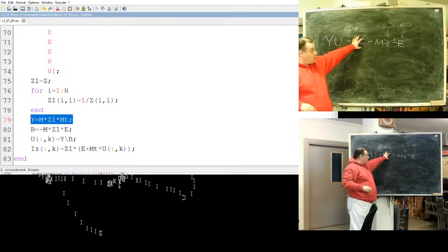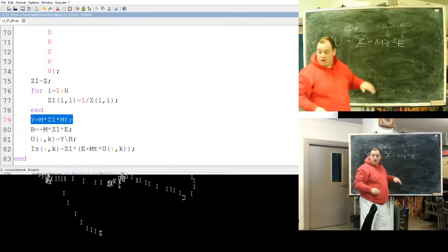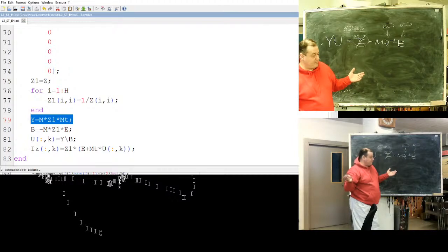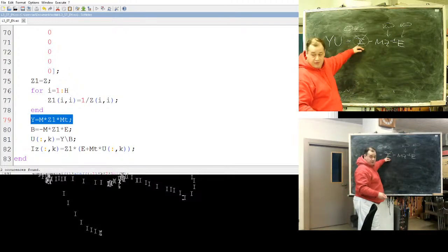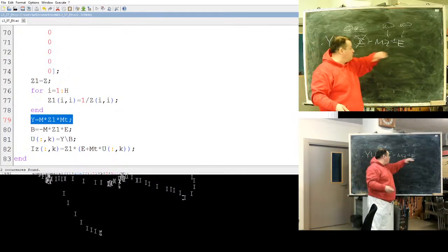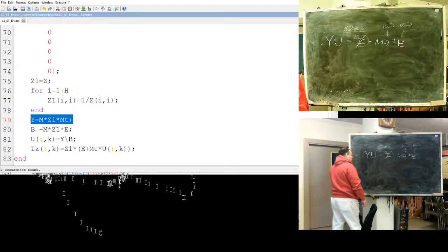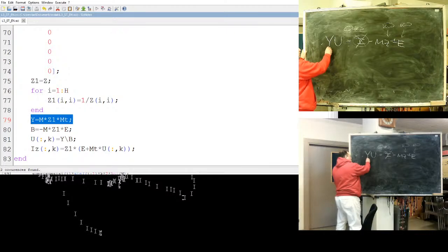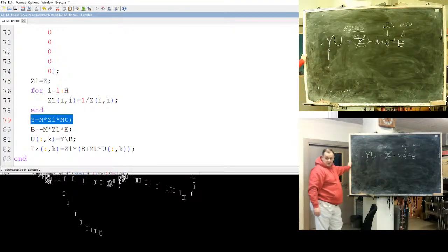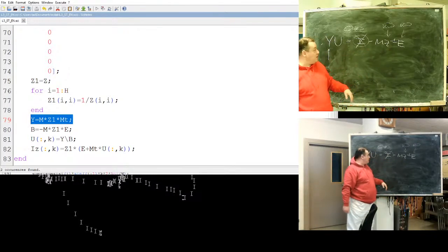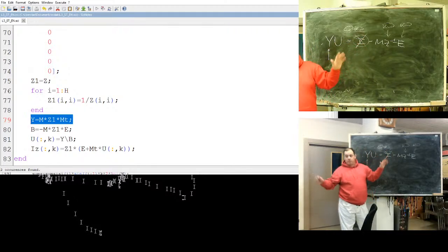This one is the current source vector, and this one is the EMF vector. I use them as necessary. When I need to represent currents, okay, I fill the current source. When I have EMF, no problem, I have a place for EMF. This one, nodal conductance matrix. Okay, Professor, but if we have current, then EMF also will be there? As needed. We can have both. But you can also only have current? If only current, this one disappears. If only EMF, this disappears. Both, no problem.